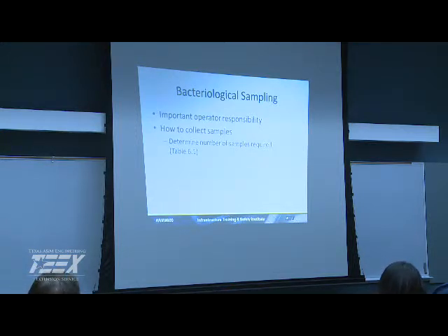And then how do we know how many samples we're going to do? Is it number of taps? Population, right? It's based on our population. How many samples are y'all pulling a month? 3 samples a month? Okay. Anybody have any big numbers? Everybody's pretty small? Okay. City of San Antonio pulls over 300 a month, so they've got a really big map where they're pulling from all over the place.